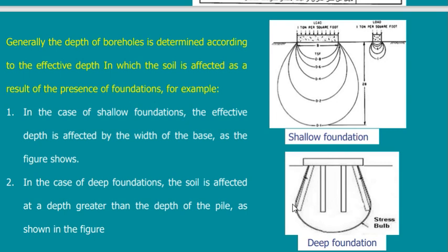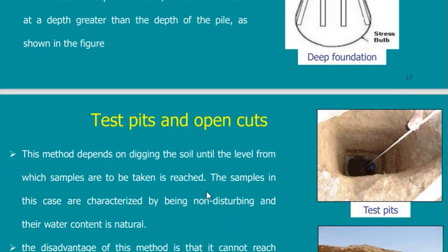Suppose you are in doubt, you don't know. Maybe you can have more or you can have less. Then you can mix. Not all boreholes the same depth. Choose some boreholes deep and choose some boreholes not deep. So in case you need them, they are there. In case you don't need them, you did not waste all of the boreholes, but you've just wasted a few of them. So this is what we need to see here.